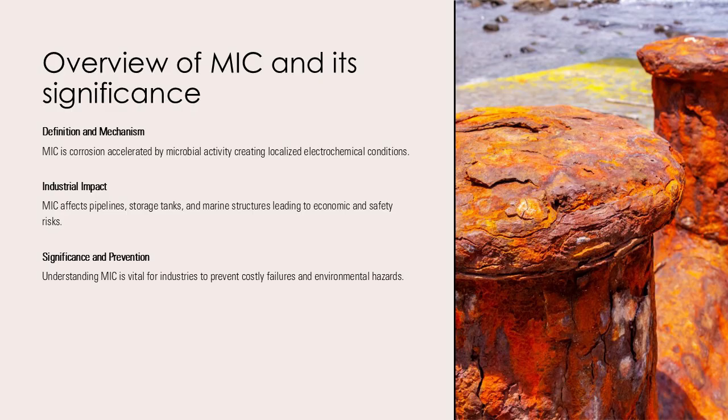Microbiologically induced corrosion or MIC is a complex phenomenon where microbial activity accelerates the degradation of metallic structures. MIC occurs in various industrial environments such as pipelines, storage tanks, and marine structures, leading to severe economic and safety consequences. The presence of microorganisms like sulfate-reducing bacteria or SRB, iron-oxidizing bacteria, and other biofilm-forming species creates localized electrochemical conditions that promote corrosion. MIC is significant because it accounts for a substantial portion of corrosion-related failures globally, often resulting in costly repairs, environmental hazards, and operational downtime.